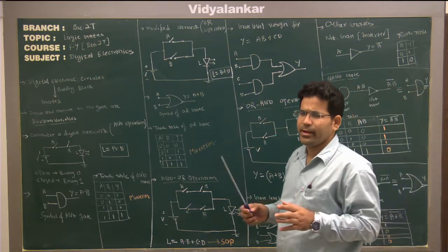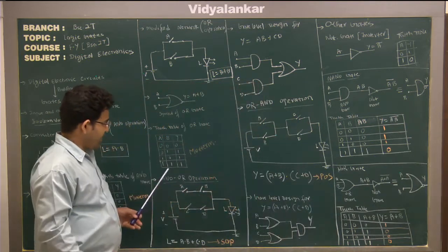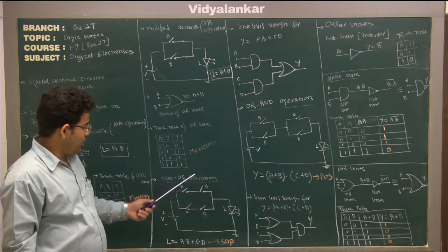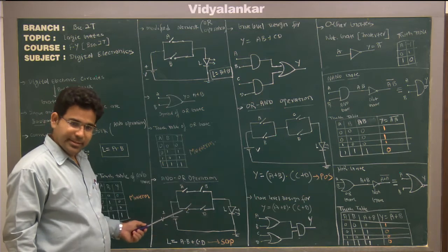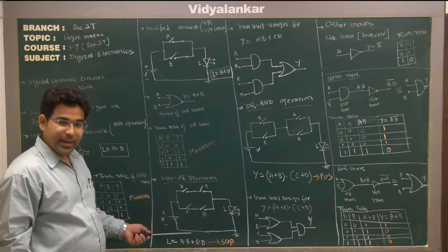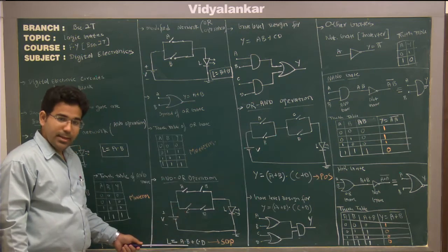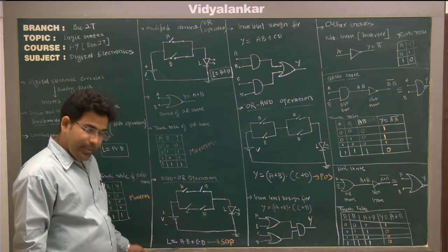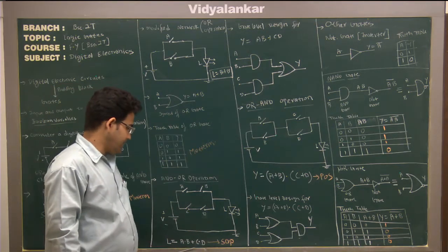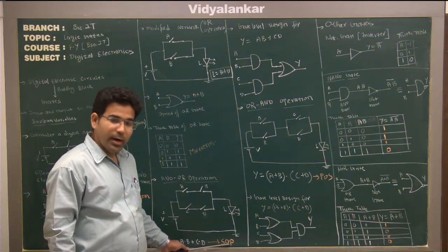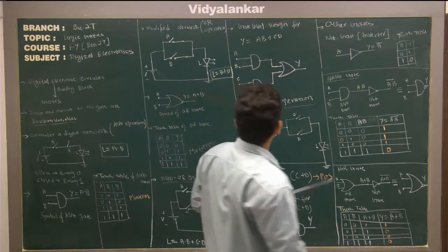If I combine this in digital electronics, we need a larger circuit. This is a very basic building block, so the actual circuit will be quite large. So, just one example where we combine both of these operations, AND and OR. What I have done is A and B are in series, meaning AND operation. C and D are in series, again AND operation. Both of them are in parallel, meaning OR operation. So my expression for getting light from the LED will be AB or CD. So AB plus, plus indicates OR, C into D. This kind of representation of a Boolean expression is known as SOP, sum of product. A into B product, C into D product, add them: sum of product, SOP representation.